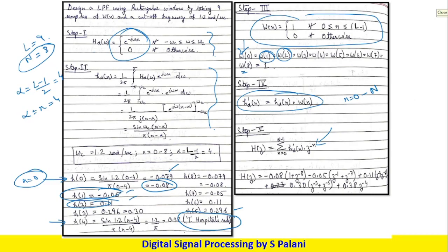In the previous case, in the Z transform equation, we needed to include z to the power of some factor so that we could convert the negative time domain to the positive time domain. However, just by tweaking this equation, we are able to get all the coefficients in the positive time domain. Okay. So once you have calculated H(z), you can then go for the realization of the filter.